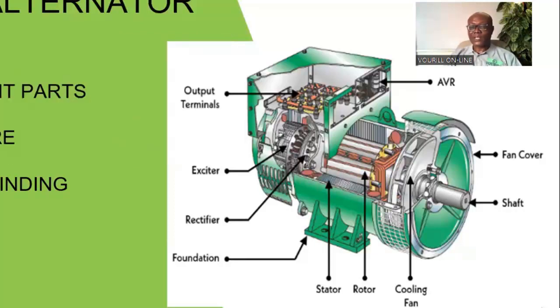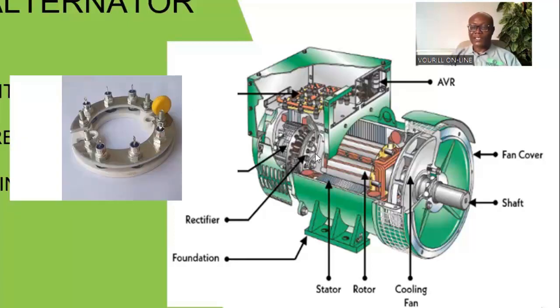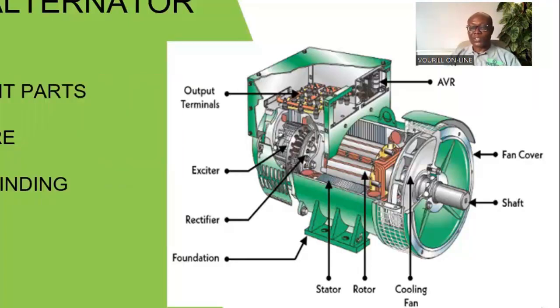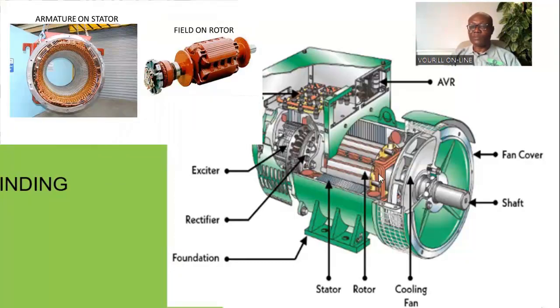The voltage produced in the exciter armature is sent to this rectifier, since we need DC voltage at the main field winding. The rectifier does the conversion to DC voltage, and it is that DC voltage that will eventually be sent to the main field winding.